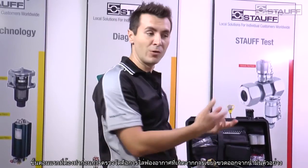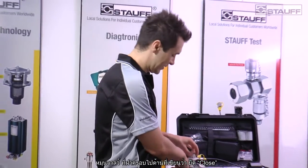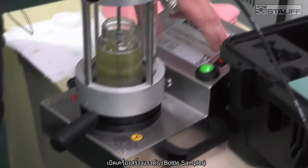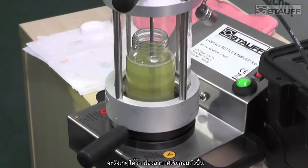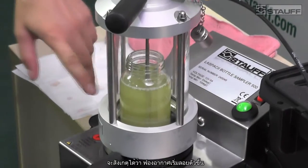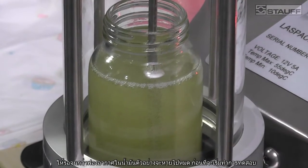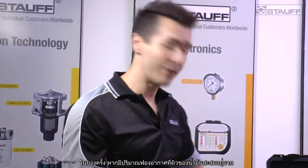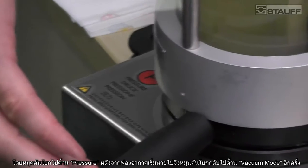First step is to remove all the air out of the sample. So make sure you close the valve. Turn the handle to vacuum. Turn the bottle sampler on. You can see a lot of bubbles up here. Make sure all the bubbles have disappeared before you commence with the test. If you have too much foam, maybe you have to vent the chamber once, make sure the foam escapes, then start again.